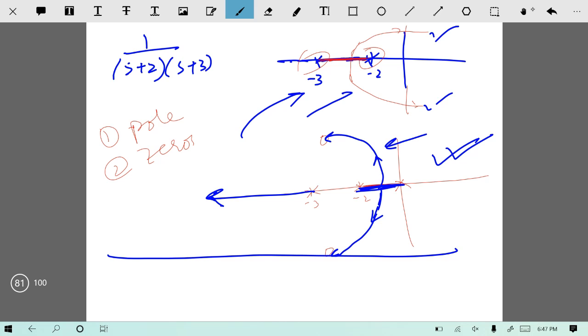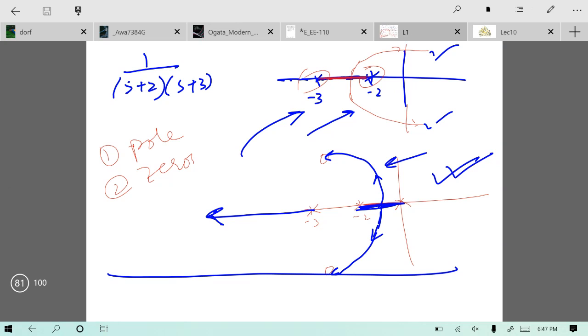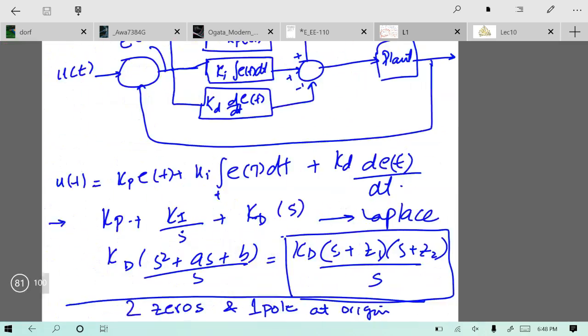However, this system has the possibility to become unstable when your process parameters or your k or your variables move beyond a certain threshold value. So you can visually see with the help of this example how a PID controller helps to enhance the stability of the system.